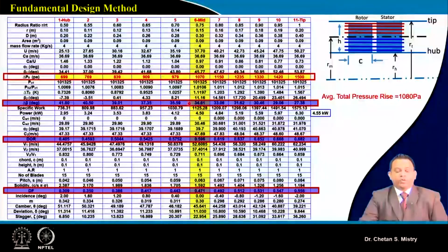Now suppose when you are doing your iterations by putting in different numbers, it may be possible that near a mid station you will have some kind of droop, or it will have an upward kind of trend. So just adjust that number. It is the designer's choice, it's your choice, you need to decide on that number. So that's how these numbers are selected.